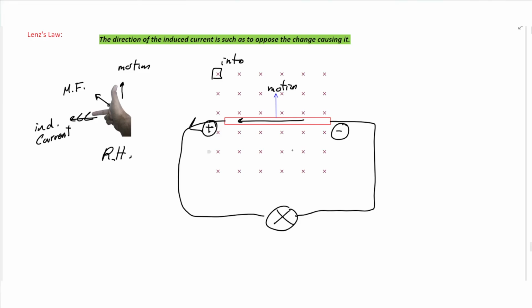And if you have a closed circuit, there is an induced current. And this induced current, you can get the direction of using the right hand rule, not the left hand rule. So if you already have a power supply and the current is already in the wire, use the left hand. If you want to get a current or induce voltage, use the right hand.